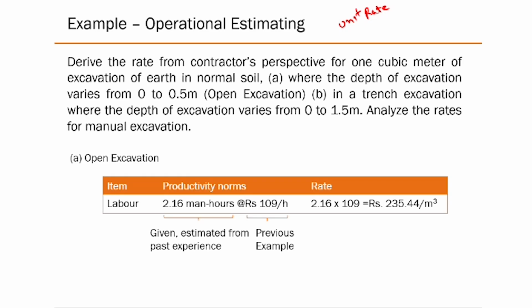Now the challenge you have here is that there is no fixed definition of what a unit is. It depends on the activity. For example, for concreting work, we saw the unit as cubic meters of concreting work. Just for material, cement bags, we calculated in terms of kgs. For the steel, we calculated in terms of again tons or kgs, right? Earthwork, you will measure perhaps in cubic meters. If you are to do work on plastering, you will measure in terms of square meters. So there is no one standard unit. The unit keeps on changing depending upon your activity, but that's how it is, right?